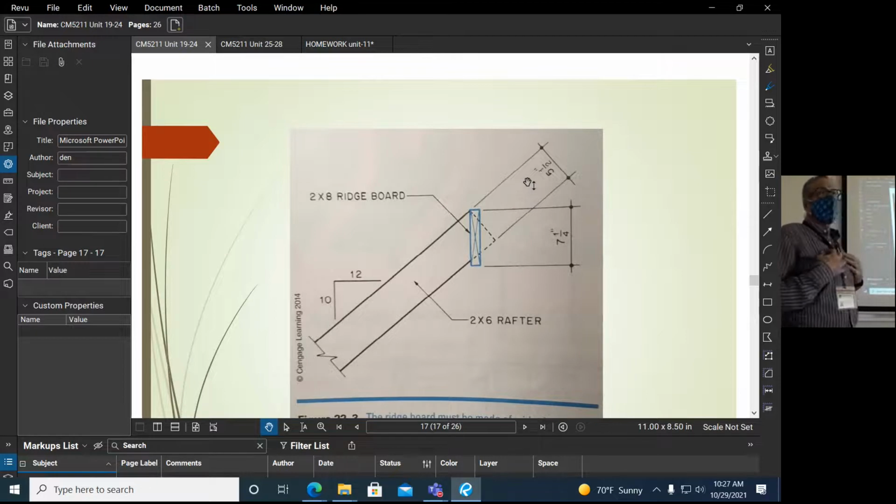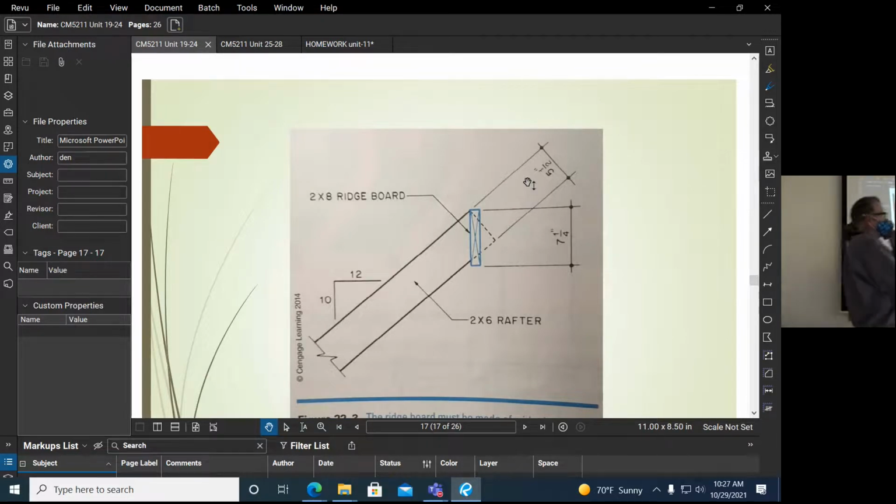So in California, even up to the most recent 2014 earthquake upgrades to our codes, we constantly have to stay on top of it and have the latest practice. Honestly, the latest practice would probably be to not even use rafters. We're just going to use trusses for mostly everything. It's just a lot faster.